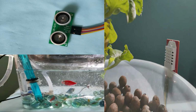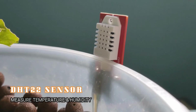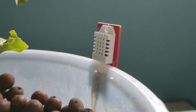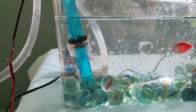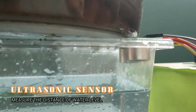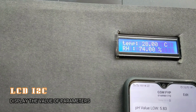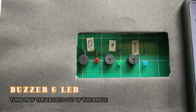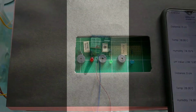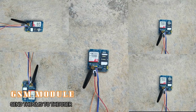In this project, it has three inputs. First, the DHT22 sensor to measure the temperature and humidity. Second, the pH sensor to measure the acidity or alkalinity of the water. And lastly, the ultrasonic sensor to measure the distance of the water level. This project also has three outputs. Firstly, LCD I2C to display the value of parameters. Secondly, LED and buzzer that will turn on if the value of a parameter is out of range. And lastly, GSM module to send the notification by SMS to the user.